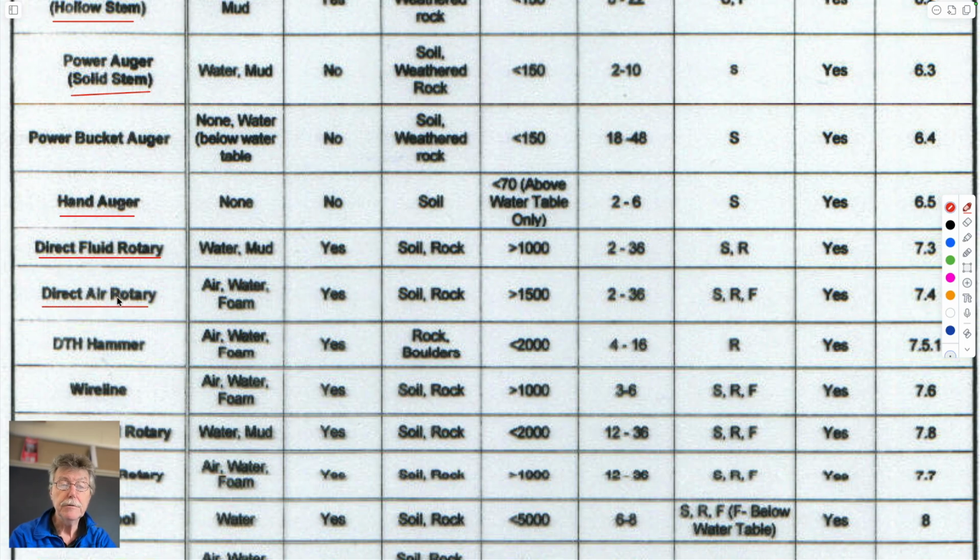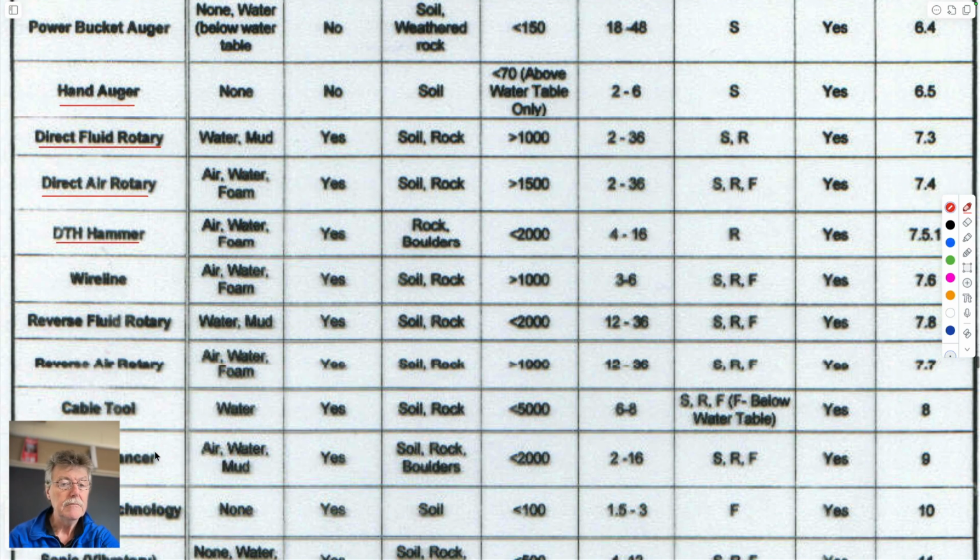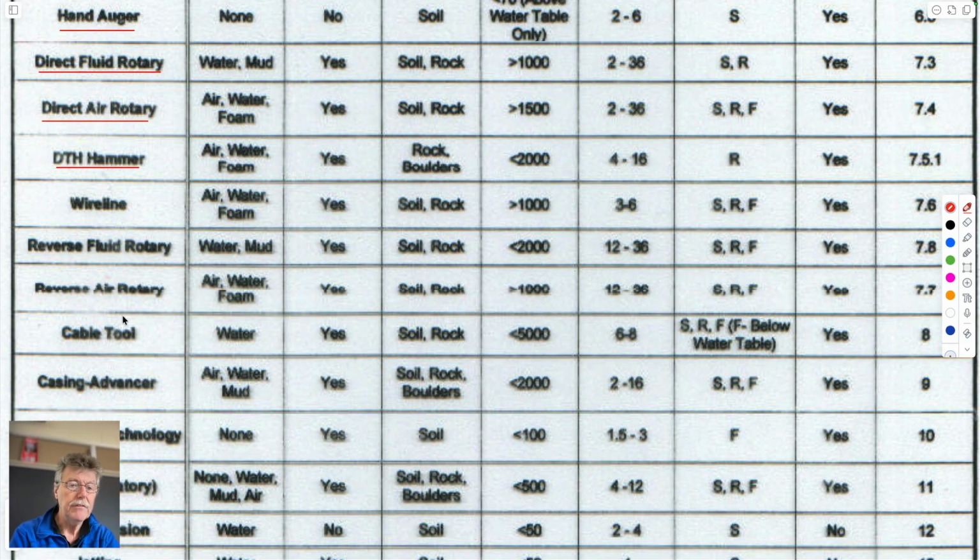Much easier to use because you don't have to supply water, which might be lost to the formation, and therefore you have to have a new supply of water to push underground. Hammer drill is just banging by percussion at the surface and having that driven into soil and soft rock. Yeah, fine. So cable tool, Drake's well, etc. So there's lots of these different things.